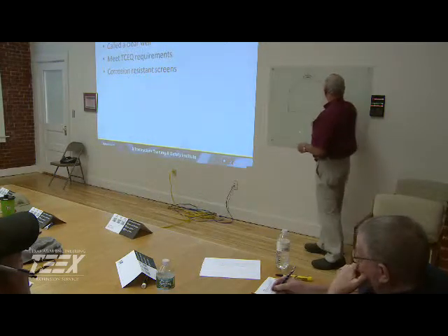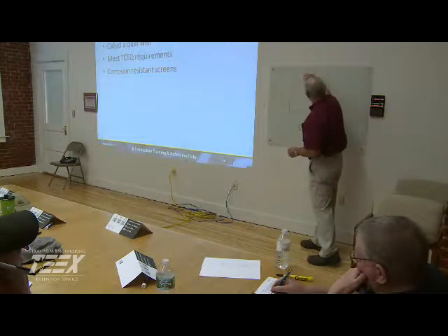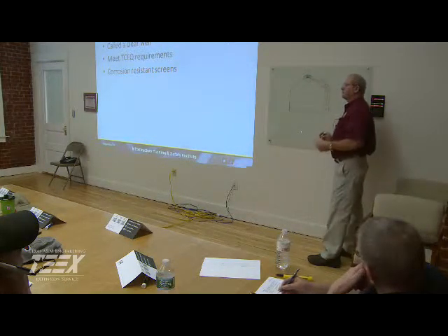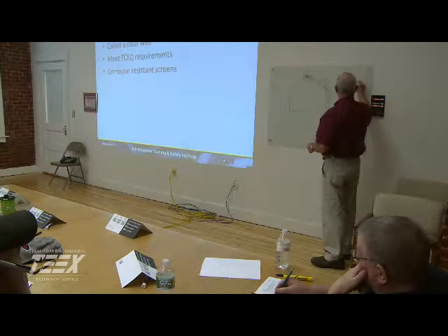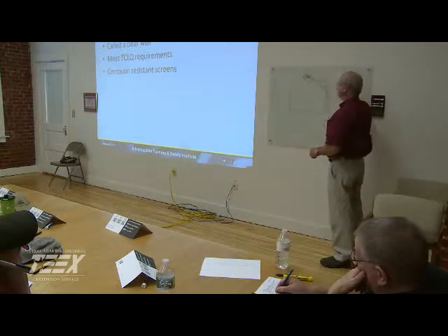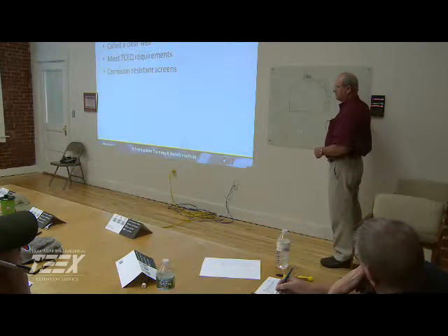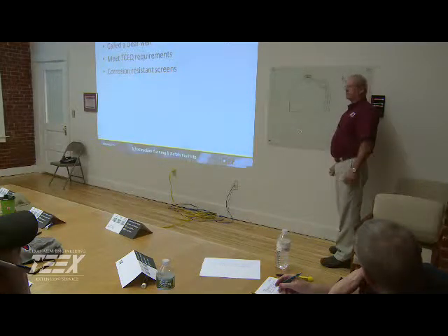Now, on your entry, let's talk about the slope of the roof. The slope of the roof is 3/4 inch per foot of run. So for every 3 foot, we must have a 3/4 inch rise. Does that make sense? And that's to allow the rainwater to run off of the top of the roof.